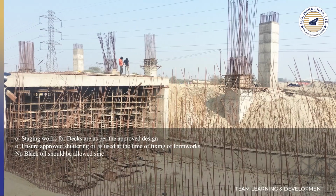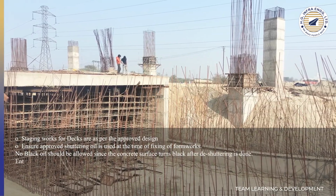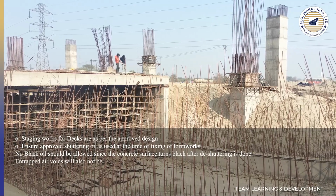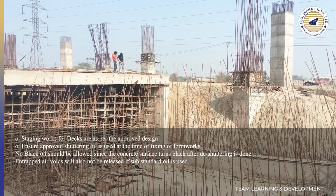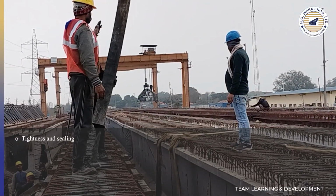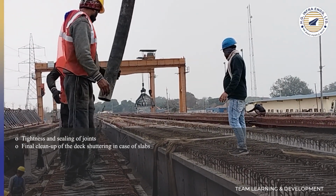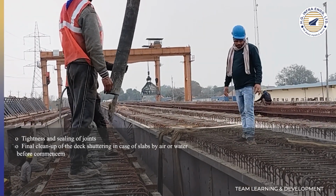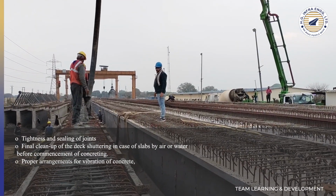No black oil should be allowed since the concrete surface turns black after de-shuttering is done. Entrapped air voids will also be released if substandard oil is used. Tightness and sealing of joints. Final cleanup of the deck shuttering in case of slabs by air compressor or water jet before commencement of concreting.